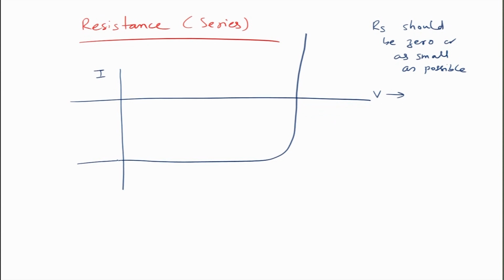So, the slope of this plot, of course, you can see you have 2 points. This point gives you a slope dI/dV. Inverse of this is the one resistance R1. Again at this point, this is at VOC. Now dI/dV inverse is equal to R2 at ISC. So, you can see that, as we have said, our ideal curve should be as squarish as possible,